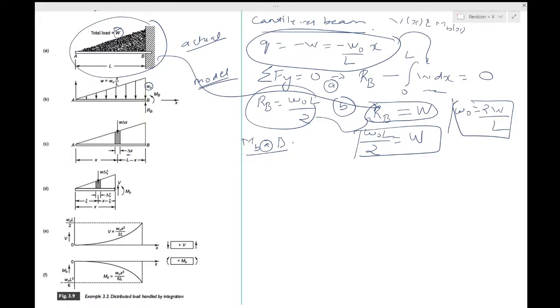So this should be easy. If you want to balance the moment about this point B, there's practically only one thing to take care of. One is the MB itself, which acts like this, and then there is the weight of the bricks, which applies this force. The lever arm would be L minus X, this particular distance from B, and you integrate from 0 to L.